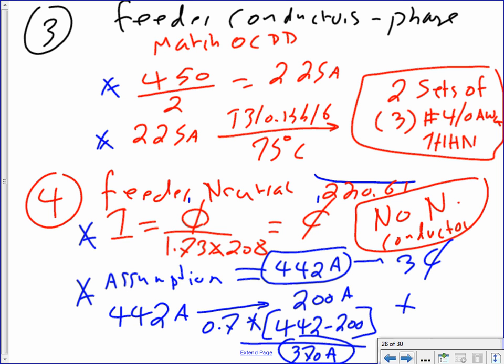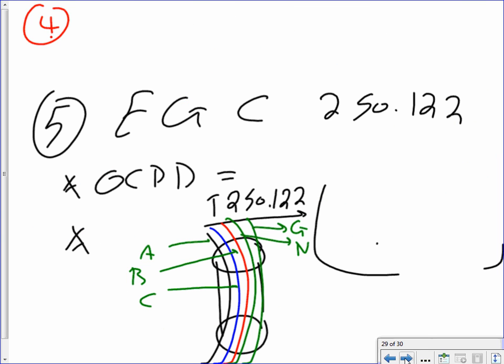So that's a decision you guys are going to make as an engineer. Should I pull a neutral? There's nothing connected, but what happens in the future? Now remember, guys, you're designing a system for 40 to 50 years. In the future, could they pull neutral loads? Yes. So that's how we do it. Any comments, guys, about this one? See my anecdotal assumption. So I got my neutral.